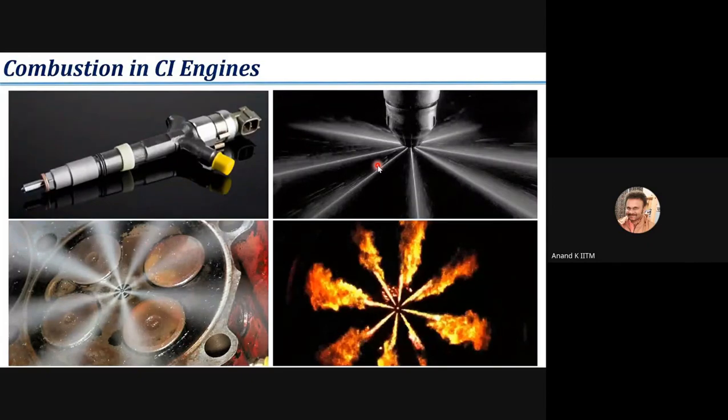Always remember that combustion will get started only with appropriate phi, that is fuel air proportion, and appropriate T. Right? To initiate combustion, I said you need two things. One, an ignitable fuel air mixture. Second, you need an ignition source to raise the temperature and start the combustion.